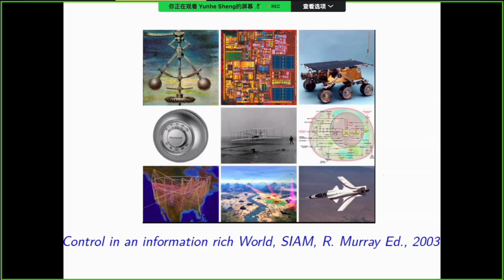So typically, we are interested in regulating the temperature in a room. We start maybe from a temperature that is very high, like 27 degrees now in summer, and we want to regulate the temperature to maybe 23, right? So what do we do? Well, we inject hot and cool air in a bang-bang manner, in a piecewise constant manner, so that the temperature is brought down from 27 to 23 and then kept oscillating a little bit around 23.